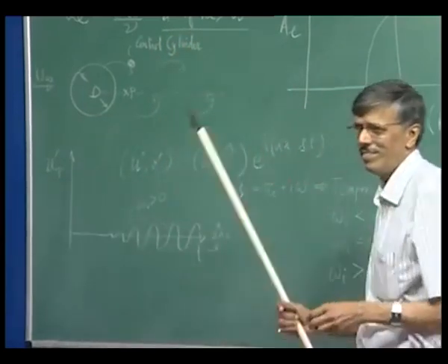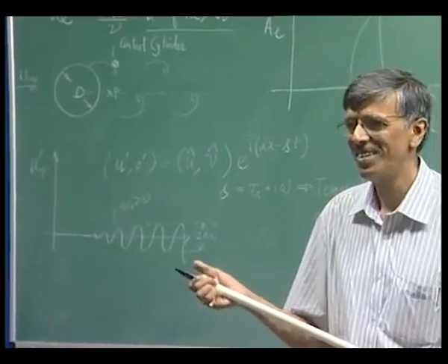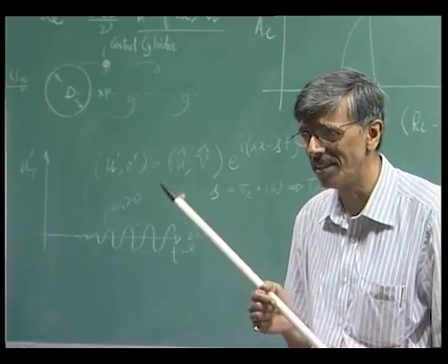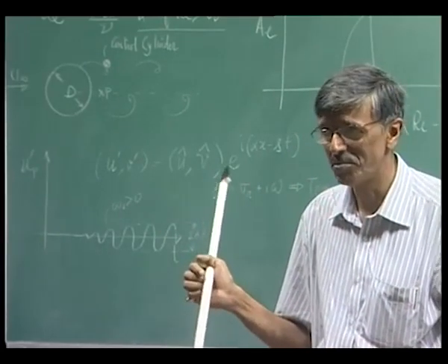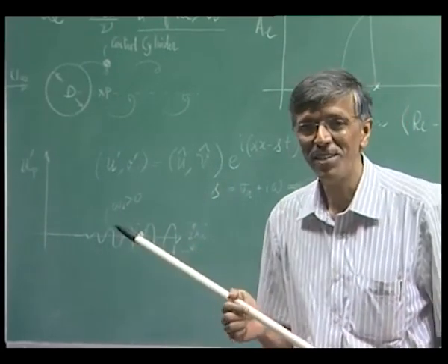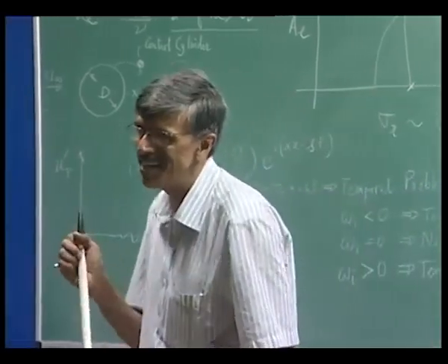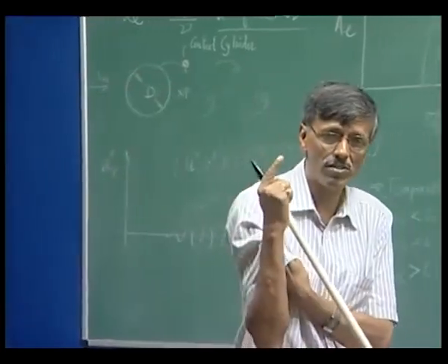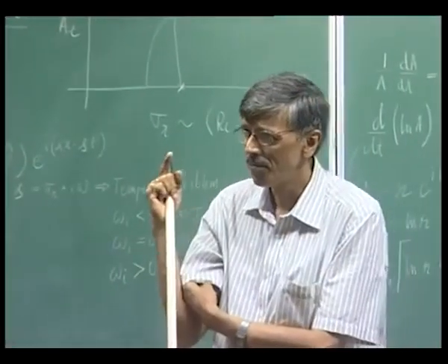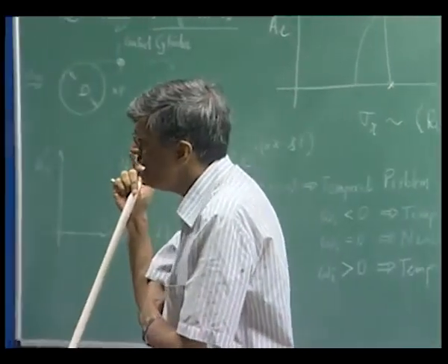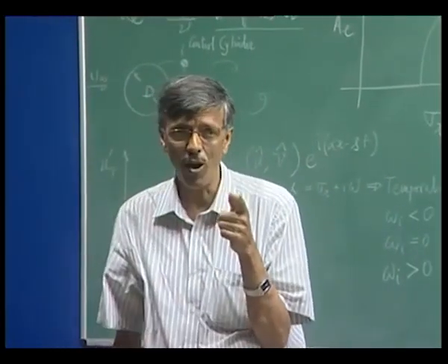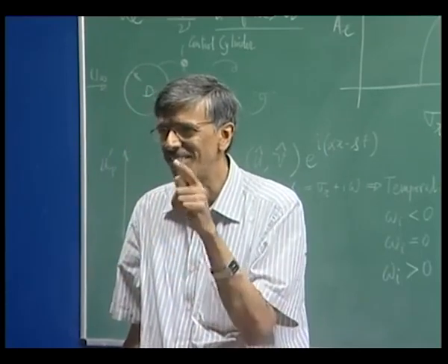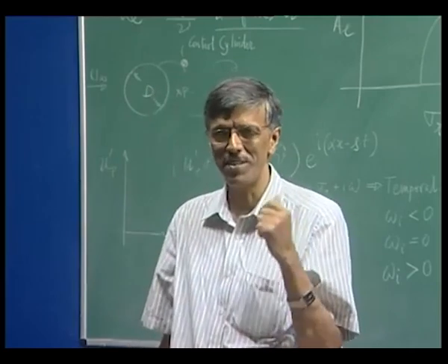And you know what? When you put such a control cylinder, many a times, if you position it correctly and the Reynolds number is less than 100, you see vortex shedding disappear. This was very interestingly found out by Courvoisier. You recall I just now showed that Courvoisier in the 40s reported a critical Reynolds number of 40. He noted that when you bring in a hot wire probe to measure this fluctuation in the wake, in some locations the vortex shedding disappears.